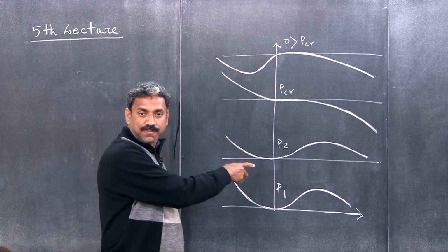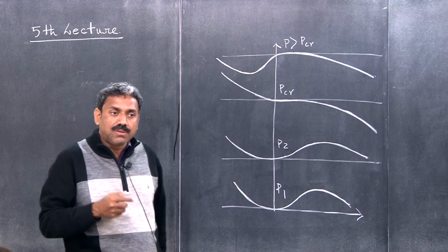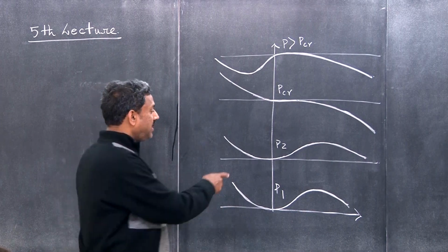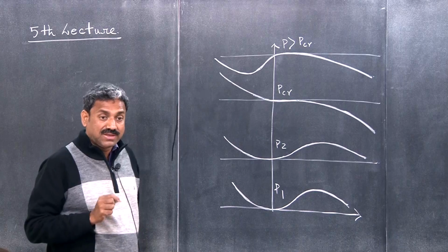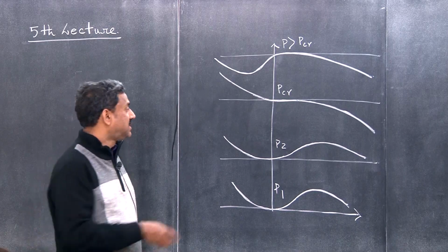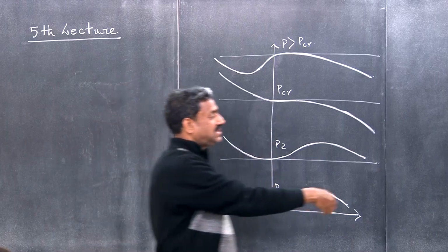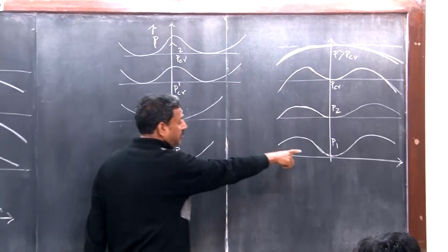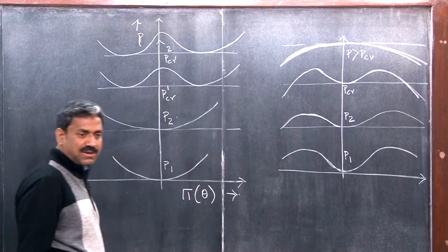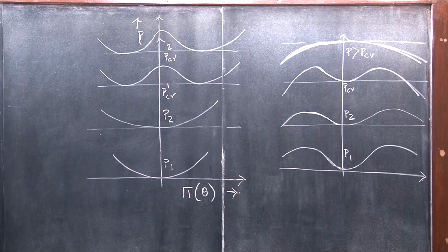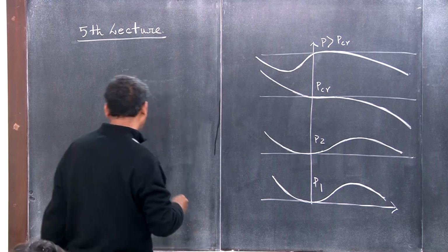And whenever these odd terms are there, it will show this notorious imperfection sensitivity. All these cases are half power sensitive. These two cases, this is insensitive, it is two-third power sensitive, right? Clear? Okay. So now we are going to consider the last type of